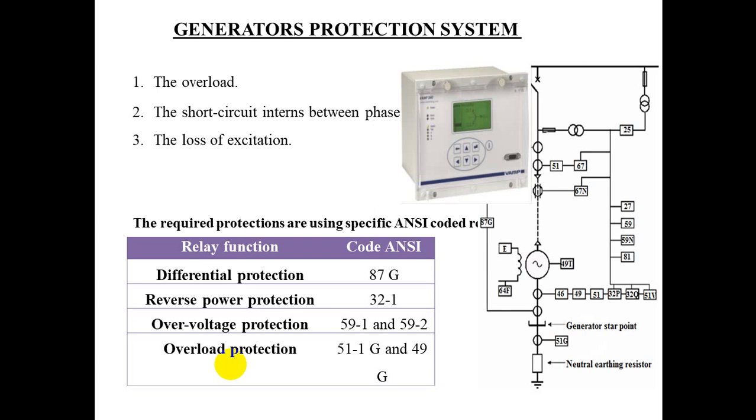Protection against difference in expansion between rotating and stationary parts. During the running up period, the rate of heating of the rotor differs from that of the casing due to the difference in mass. As a result, the rotor expands at a different rate to the casing, and it is necessary to overcome this unequal expansion.